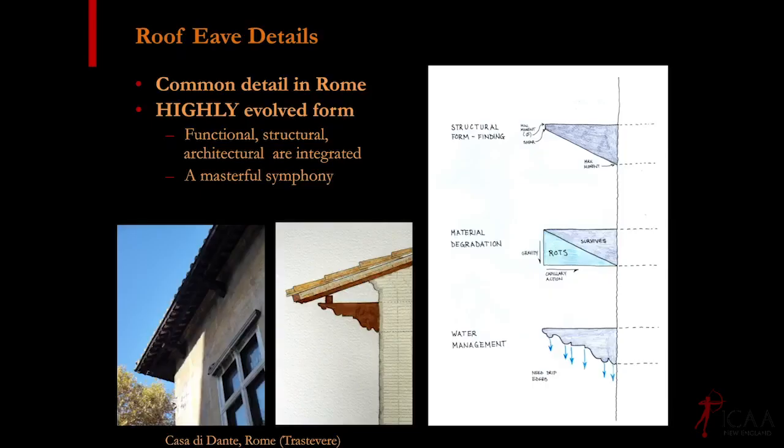And then you might think, well, you could just cut it off at that straight angle. Why do you need all these little ornamental doodads? Isn't that just ornament? Well, those are beautiful, but they're not strictly ornamental, because when this does get wet, what you really want to do is shed that water as quickly as you can. So those create a whole series of drips to get that water off.